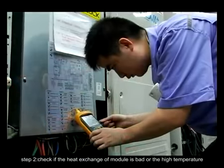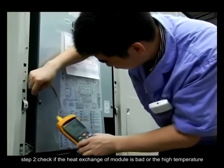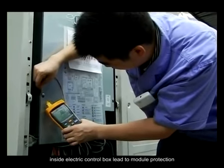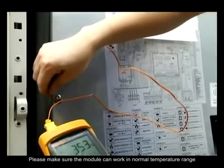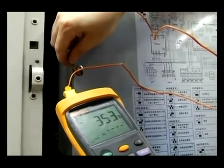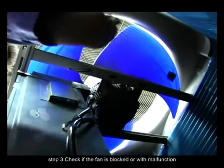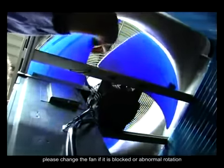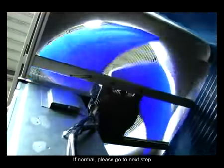Step 2. Check if bad heat exchange of the module or high temperature inside the electric control box leads to module protection. Please make sure the module can work in the normal temperature range. If it is normal, please go to the next step. Step 3. Check if the fan is blocked or has a malfunction. Please change the fan if it is blocked or rotates abnormally.